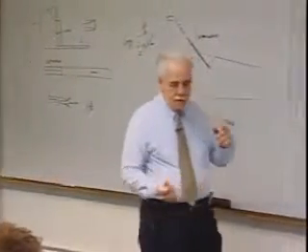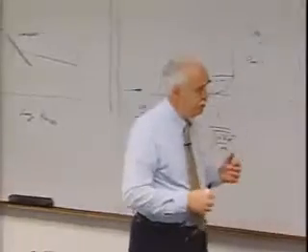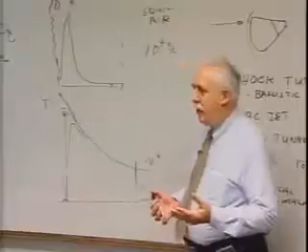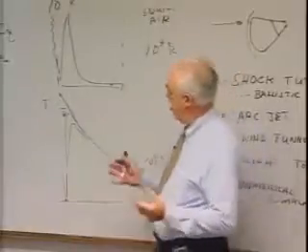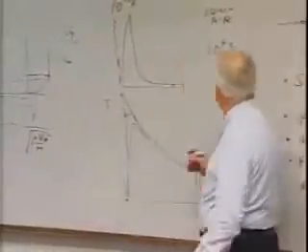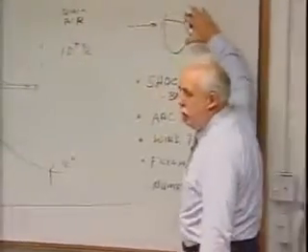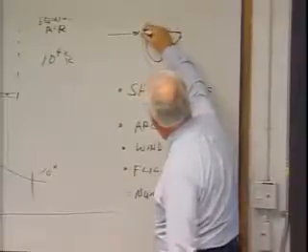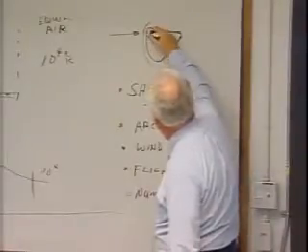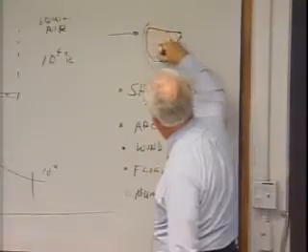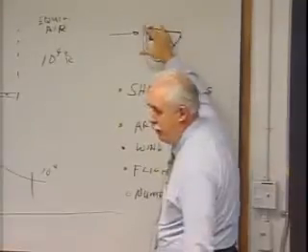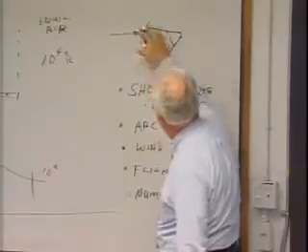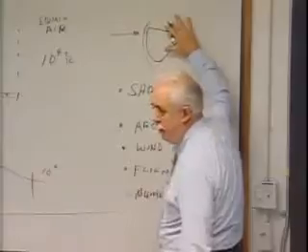Frankly, I'll show this in charts, in terms of the design approach to getting the aerothermodynamic environment at flight, we used the same technology that we used in Apollo, and that was we take a scale model and go into a wind tunnel. Now this is a blunt vehicle, and so if you look at it as an inviscid flow, the close to normal shock entropy is basically the entropy of the entire body. And so the normal shock or strong shock gas dominates the flow around the vehicle.